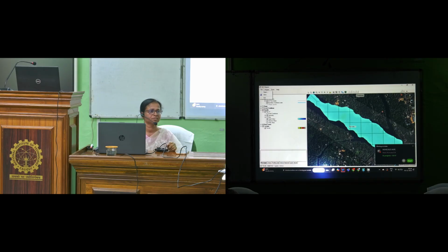Okay. And it's also a good idea to start with steady state flow, just to learn, so the system may not be confusing. Then cross section, 1D steady state flow if you want to learn that. Then define cross sections and see the profile of the water that's moving. And then by changing the Manning's roughness, you can check whether the water is moving fast or slow.